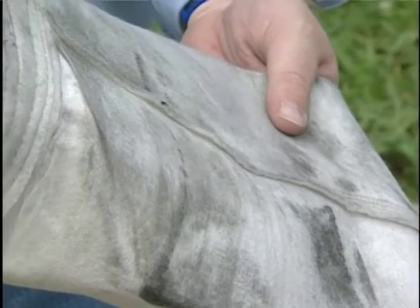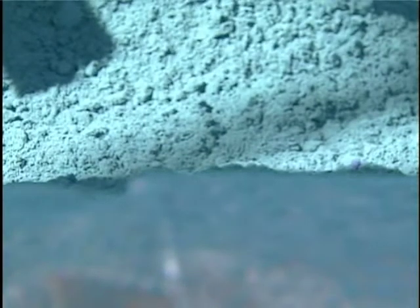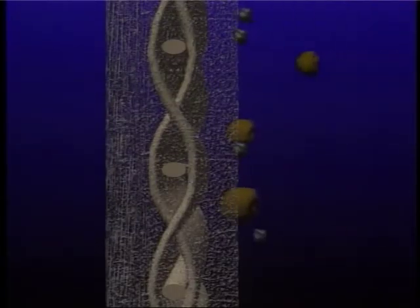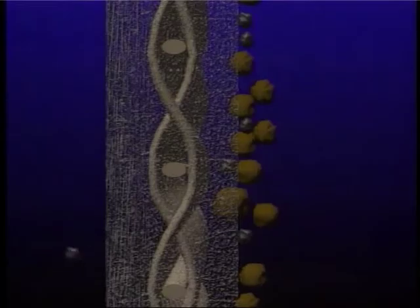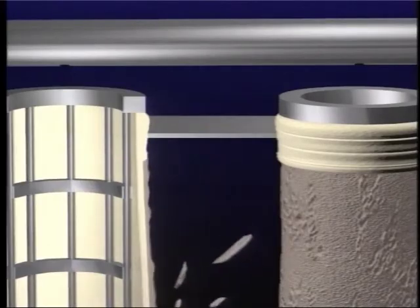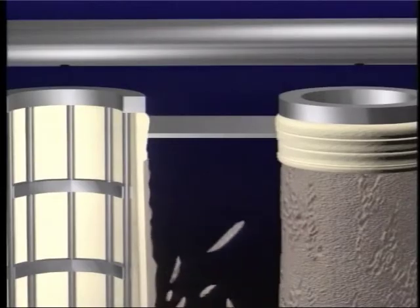The fabric used in pulse jet collectors is usually a heavyweight felted fiber material. The fiber that is used is again chosen based on the characteristics of the particles and the gas stream, and on its ability to withstand the forces of cleaning. As with woven fabrics, the collector's ability to remove small micrometer and submicrometer particles is due to the accumulated dust cake and not the fabric itself. The fabric is usually pulsed several times an hour to remove some of the dust cake, but may be pulsed much less frequently when the dust concentration is low.